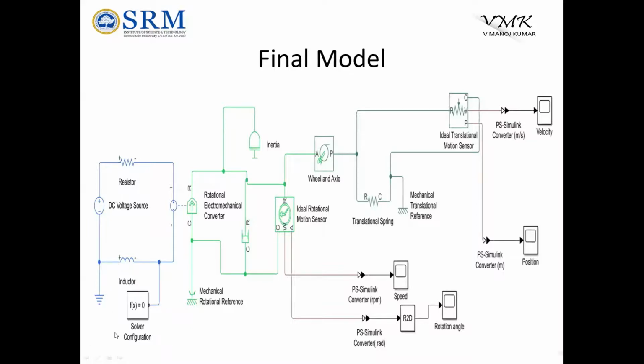Okay, so you know ODE45, ODE15. You have heard about the Newton-Raphson method in your mathematics subject. If you have studied optimization and all, you would have heard about the Newton-Raphson method. That method is used here to run my simscape model. This is a part of simscape. Whatever simscape model is done, I need to give this solver configuration on default. I can change to ODE45 or ODE15 or some properties here according to my requirement. On default, take it. Don't change the property unless you are an expert in that area. Okay, you understood the model.